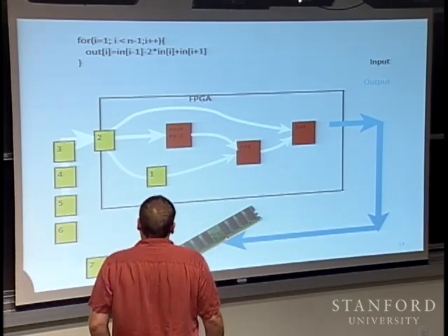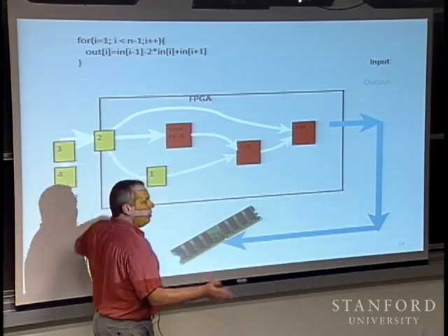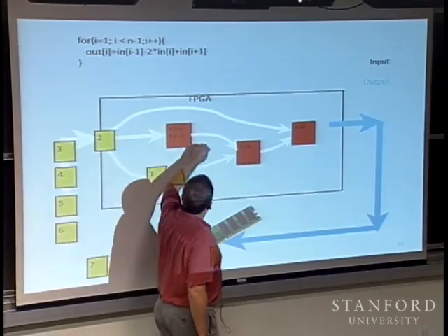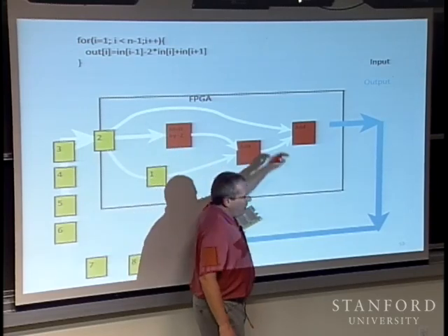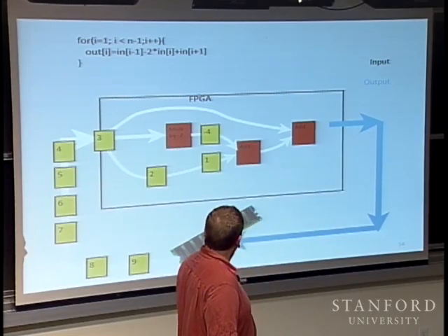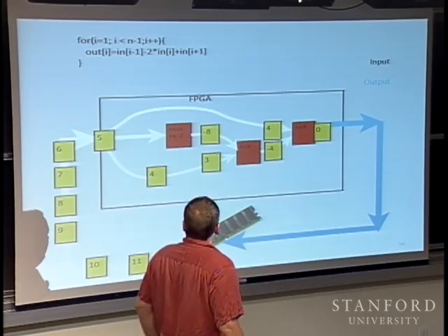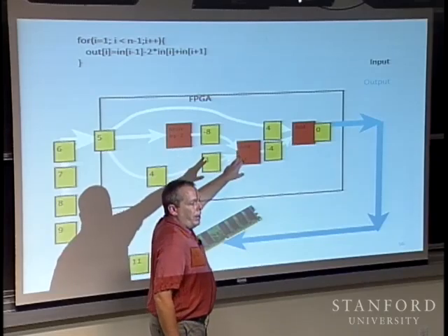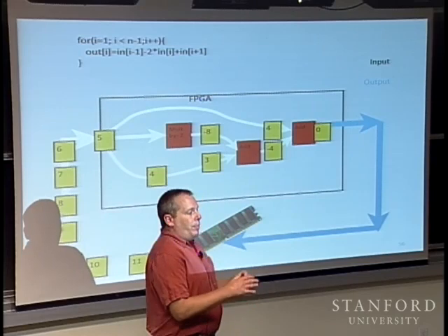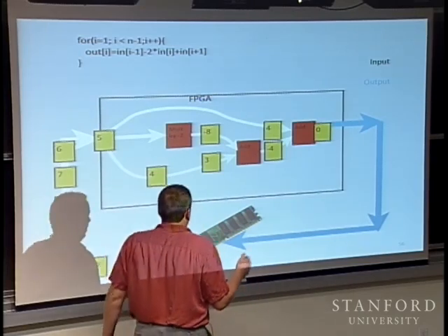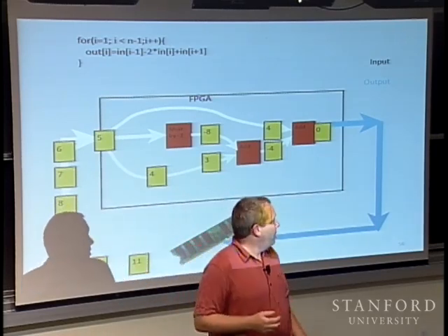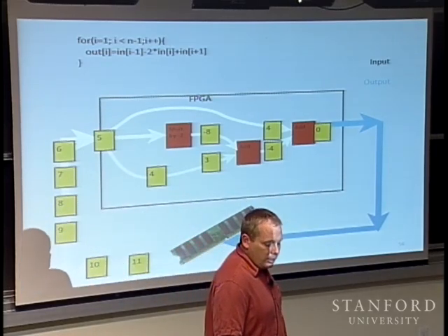As an example, I'm going to flow an array that's 1, 2, 3, 4, 5, 6, 7 out of this memory. I'm going to build a series of compute units. One's going to multiply by -2, and then a couple of adds. We flow the data through this, and we're basically building a big pipeline. What the FPGA enables you to do is, if you have a big enough pipeline, even though its clock speed is really slow, if your pipeline's a couple hundred stages long, then even with that low clock frequency, it can suddenly be a big winner.